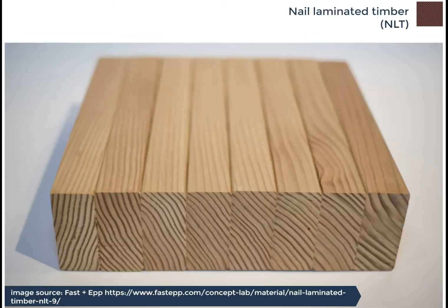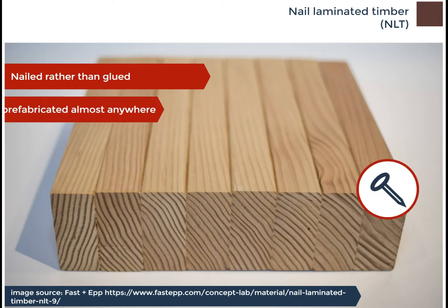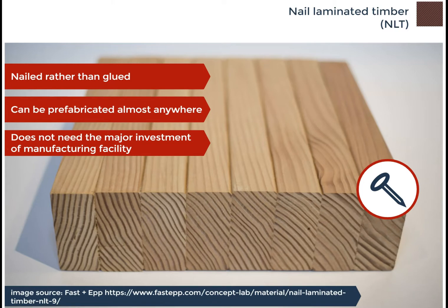Nail laminated timber, NLT, is similar to CLT but, as the name suggests, nailed rather than glued, which means it can be prefabricated almost anywhere and does not need the major investment of a manufacturing facility.